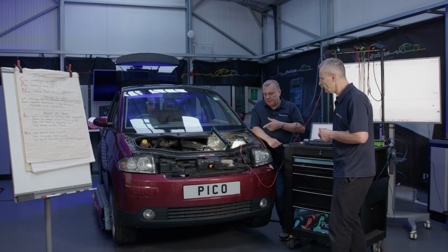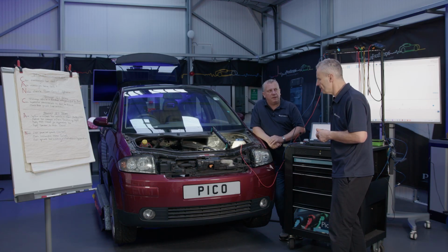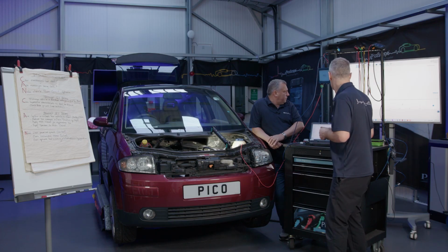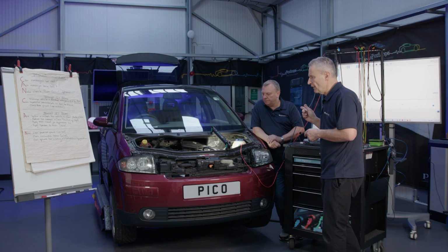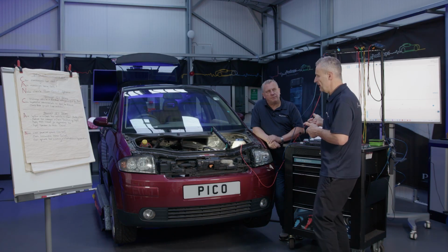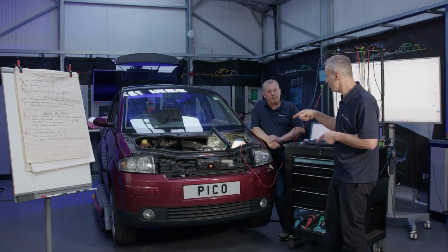But personally, I feel this is a little bit, I'm going to say the word flaky, because we got 506 milliohm. Is that good or bad? We don't really know. So we need something a little bit more conclusive and something a little bit more accurate. So at this point, more accurate could be the milliohm meter. I think we'll do that test.